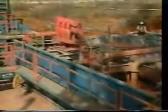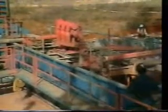Cleaned of large cuttings, the mud may then be sent to a degasser, where small amounts of gas picked up from subsurface formations are removed. Desanders, desilters, and a centrifuge all employ centrifugal force to remove progressively finer particles from the mud. With all these solid particles removed, the mud is now ready to repeat its journey through the system, starting again at the pumps.